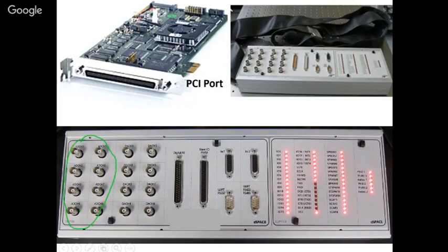You can give many signals at the same time, that is, 4 signals can pass through the same channel. When I show some more slides with the block diagrams, you will understand more clearly. Apart from that, you have digital to analog converters also. When you want to take outputs, you can convert the digital value into analog. You have digital input-output terminals, and PWM terminals where you can generate PWMs. RS-232 ports are also given, which you can use when you are doing robotic applications.